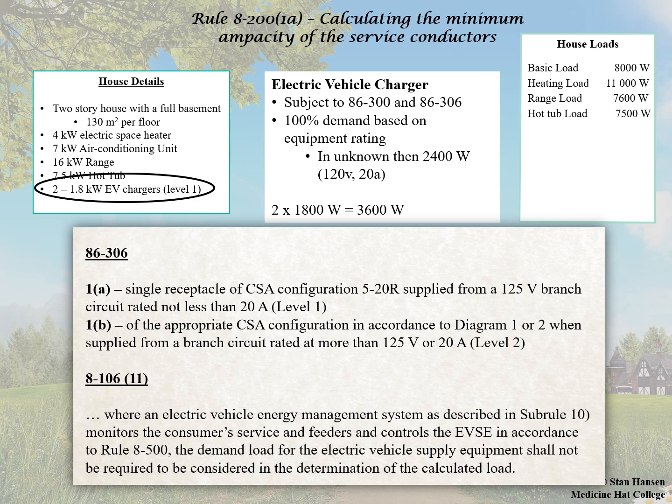With our service, we do have 2 chargers. They're both rated at 1.8 kilowatts. We're going to put them in at 100% demand rating. Therefore, we add 3,600 watts to our list.